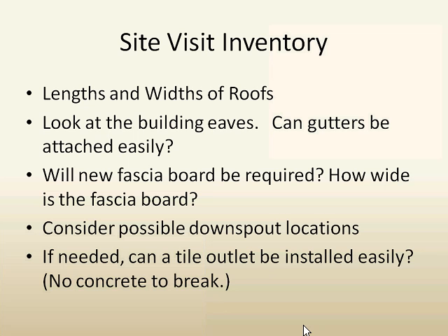Can a tile outlet be easily installed, or are you going to need to break concrete to put one in? If that's the case, it may be better to run a lateral collection line down the length of the building, so you only have to go down into the underground outlet in one place.